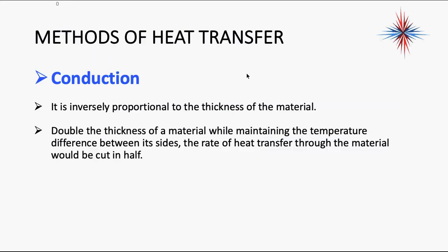Conduction is inversely proportional to the thickness of the material. Double the thickness of a material while maintaining the temperature difference between its sides, and the rate of heat transfer will be cut in half.